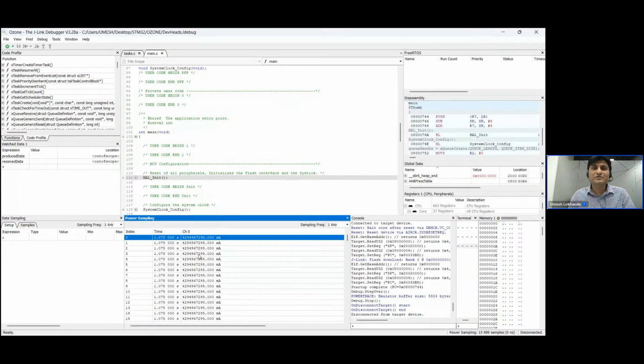when we use a trace buffer to collect the data from the microcontroller, and that too we are using the on-chip trace buffer. In the debugging, the on-chip trace buffer has very small size. That's why people pay huge money for this expensive debugger, right? Because either you will have to have a bigger trace buffer that is probably on your trace probe, or it could be directly in the host PC.